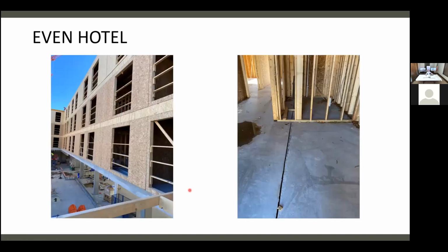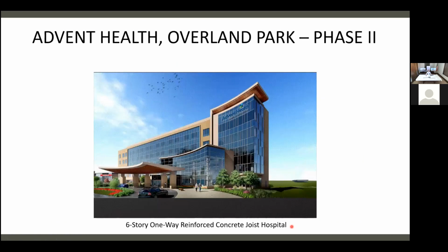And a lot of podium work is going on around the country. We have 3 stories of wood up, and they framed over the pour strip. You can see that on the right. Not even grouted yet. We're moving just a little bit, depending on the system. Max that I've seen is maybe 5/8, 1/2 inch, but we're seeing things at 1/4 inch. The slabs don't move that much, but if you don't allow for that movement, your slab's going to crack and have poor performance, okay?